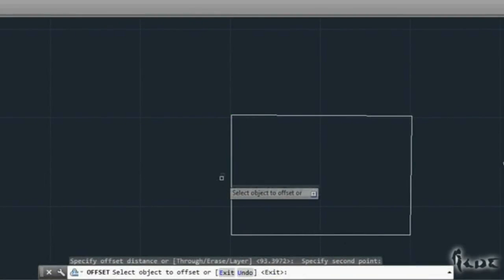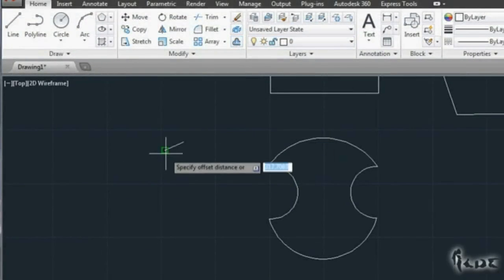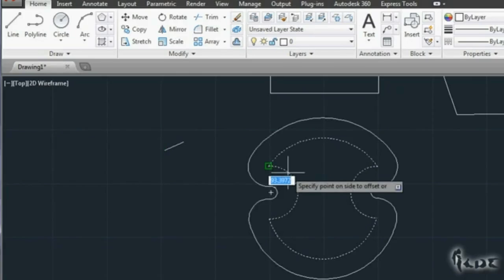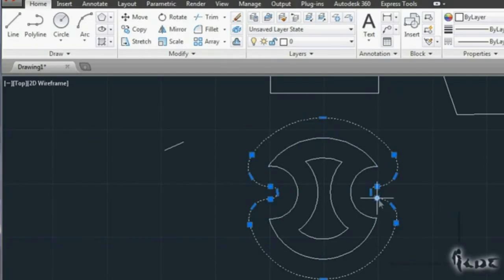After pressing Enter, you will have to select which object to offset. Once done, you will add a parallel line at the distance set. This works with polylines as well. A new object will be added at such distance kept constant, and it will be the same kind as the object selected. If you selected an arc, you will create a parallel arc, and so if you work with a polygon.